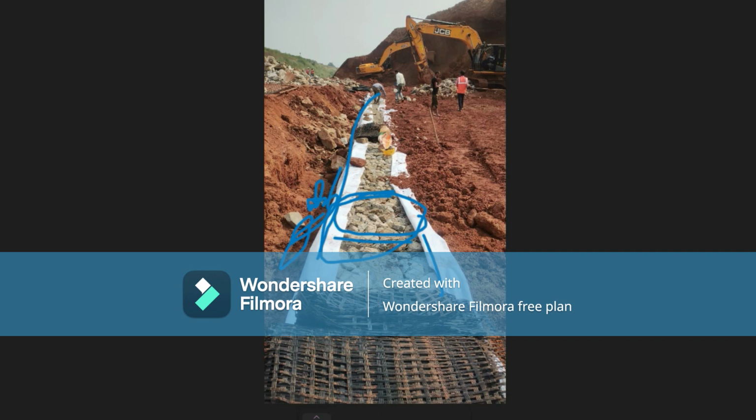Each box overlaps with another two boxes for every layer, with a 2 meter overlap, and geotextile is provided along the vertical of the wall to prevent the separation, so fine soil cannot penetrate into the gabion box.